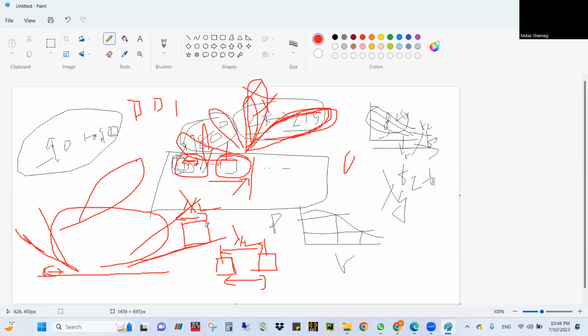So ultimately what we are doing is constructive interference, or we can say this all will be coherent and then form this beam. And at the same time, you should not have any other beams. So in order to do that, we have to optimize the spacing between the elements and the weights. The element characteristics also matter a lot, because the thing is,